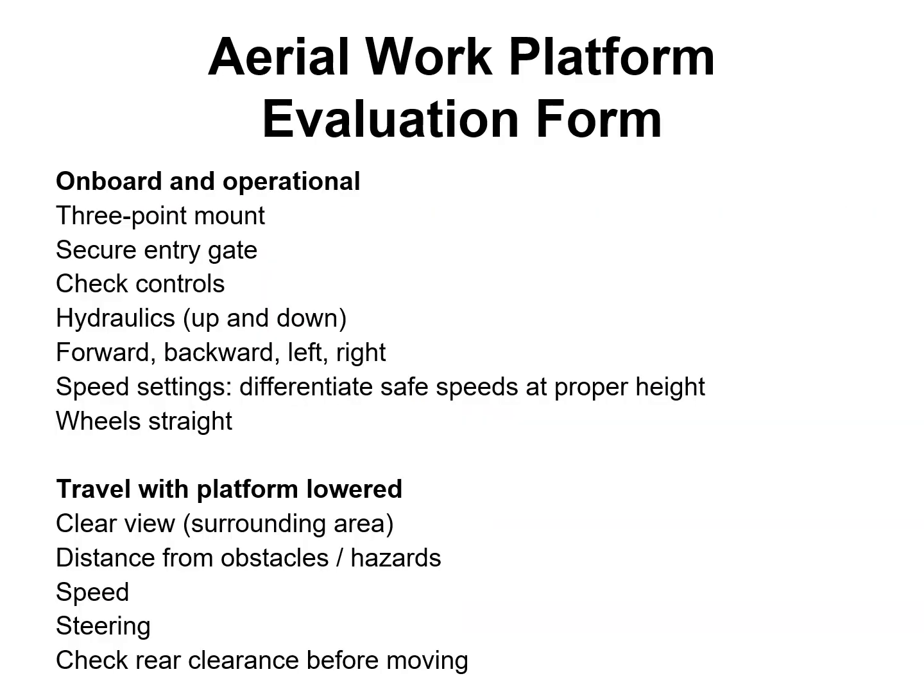Aerial work platform evaluation form, onboard and operational. We want to use 3-point mount. We want to ensure the secure entry gate works. We want to check the controls. Make sure the hydraulics are in good condition. We want to make sure the controls operate forward, backwards, right, left. We want to ensure the speed settings and proper height.